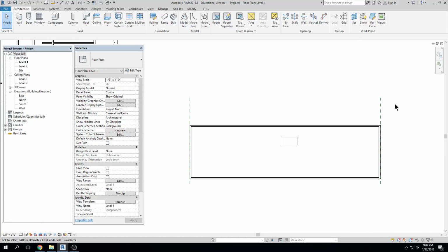So I use reference planes in combination with dimensions all the time to get my dimensions, my objects, my buildings dimensionally correct, right? It's kind of the ray or the X line of AutoCAD, except that you can leave these in here so visually you can tell what's going on and see that things are where they need to be, right?